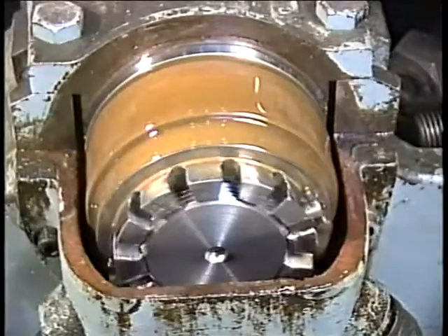Now, the high rate of bearing problems shouldn't be blamed on the inadequacy of bearings as a machine part. Bearings in gear units usually fail because the tolerances associated with a bearing are often more critical than the gears in a gear unit. For this reason, bearings are more sensitive to some of the conditions that can damage gear sets. So the bearings may start to fail before the gears in the unit become affected. Let's begin by quickly listing some of the things that might lead to bearing failure.